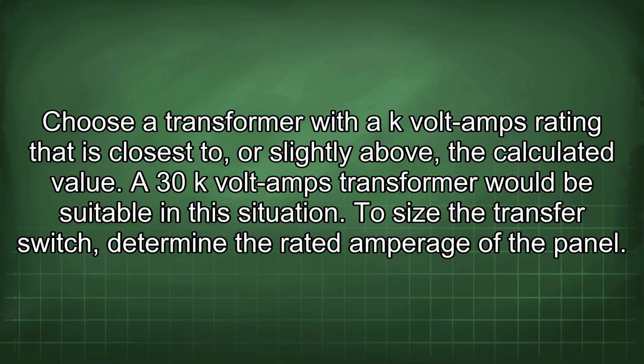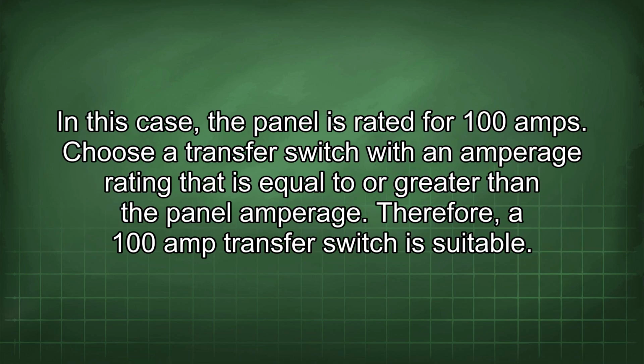To size the transfer switch, determine the rated amperage of the panel. In this case, the panel is rated for 100 amps. Choose a transfer switch with an amperage rating that is equal to or greater than the panel amperage. Therefore, a 100 amp transfer switch is suitable.